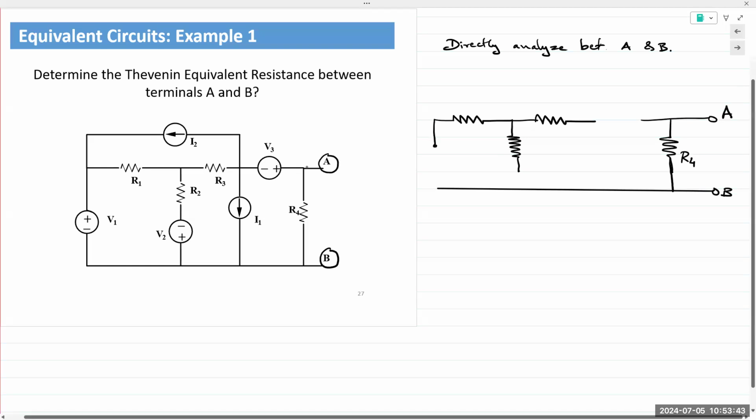So we remove the voltage source and place a wire in its place. And the same thing here. And then the current source, of course, you don't have to draw anything out. This is where the current source was connected, so we may as well not draw anything. The current source is removed. This was the place where I1 was connected. This is R1, R2, R3.